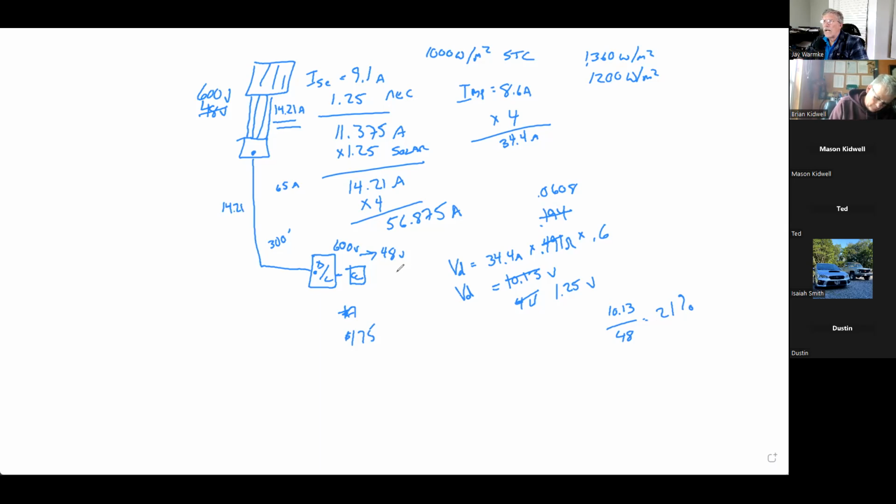Okay, I know that was a lot of stuff in there, but hopefully that will give you a sense of why we're trying to learn all this stuff. We're really trying to learn it just so we understand how to wire the system safely. So go through some of these practice problems and make sure you begin to understand how sizing the wire impacts things, why we have the safety margins, and how voltage drop affects it.